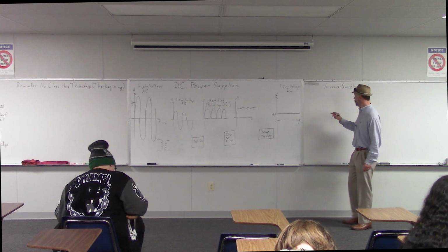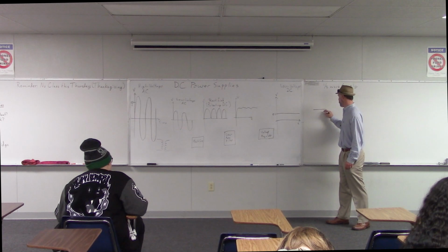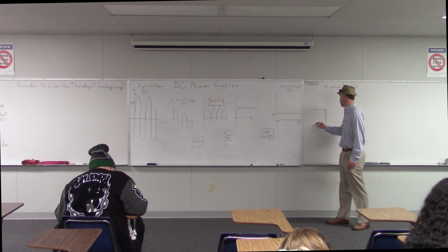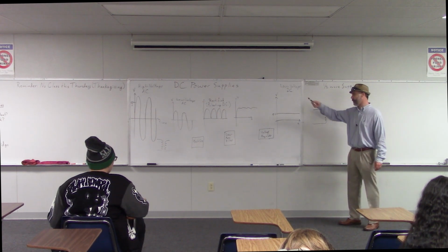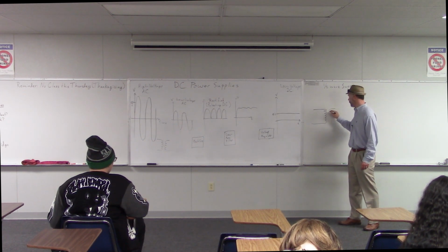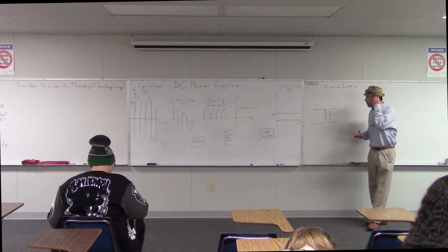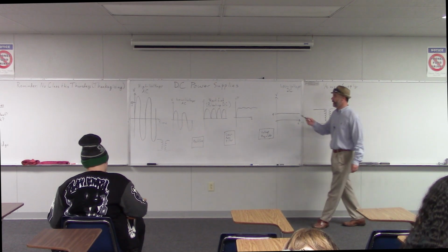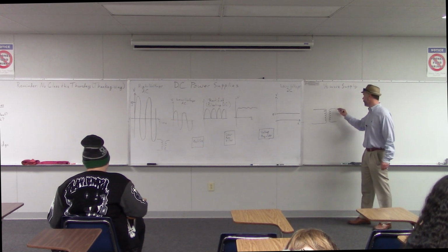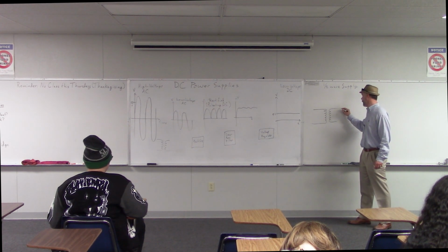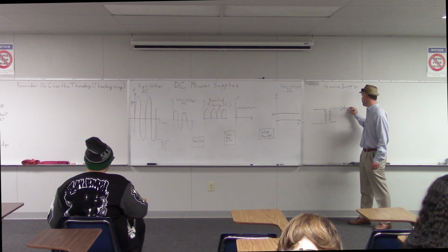So the first part of the half-wave power supply is a transformer. This is going to be the first part of all of the power supplies that we look at. Remember, this takes the high voltage AC and turns it into a low voltage AC signal. And then the next part of the half-wave supply is the rectifier. For a half-wave power supply, the rectifier is just one diode. That's all it is.